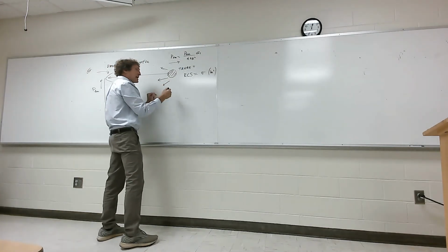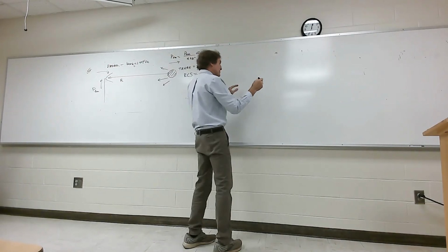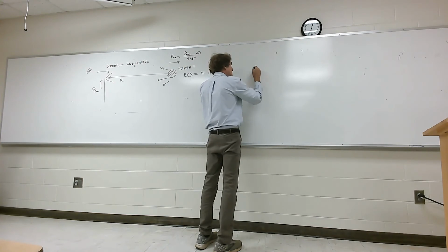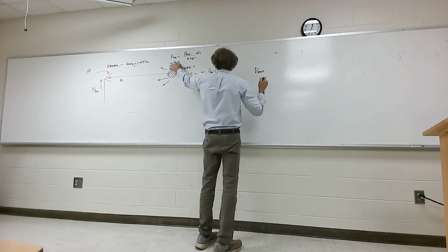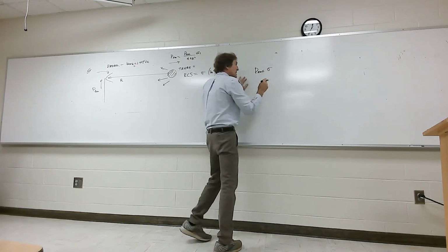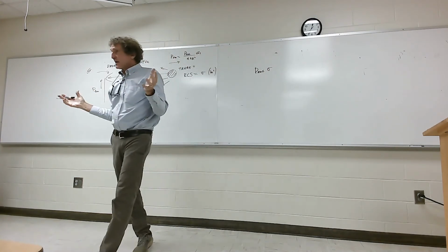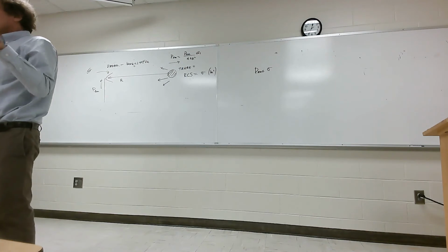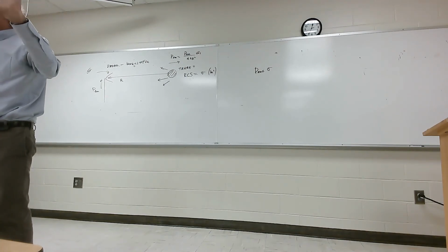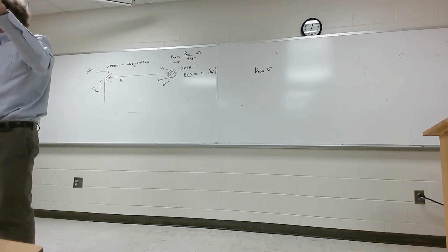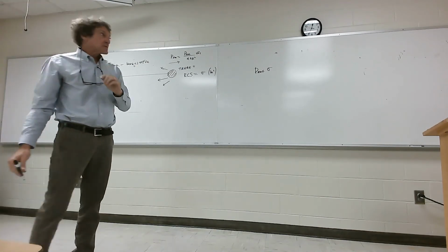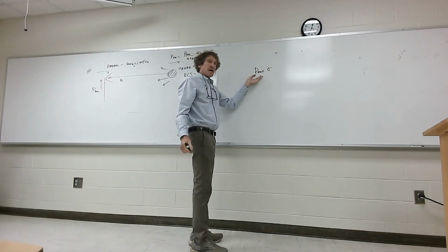And the re-radiated power density, I'll just take you through this. I come at it and I have an average power density, P-ab, right? That's right here. Then it's times sigma. That's the total amount of power re-radiated. Do you follow me? That sigma value is like the aperture in terms of the size of the antenna. It's in meters squared. This is how much power is going to be re-radiated.